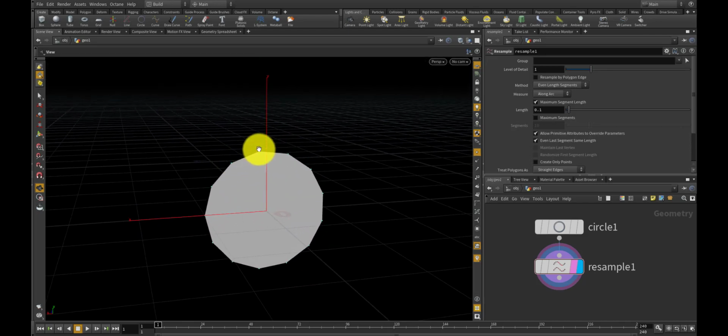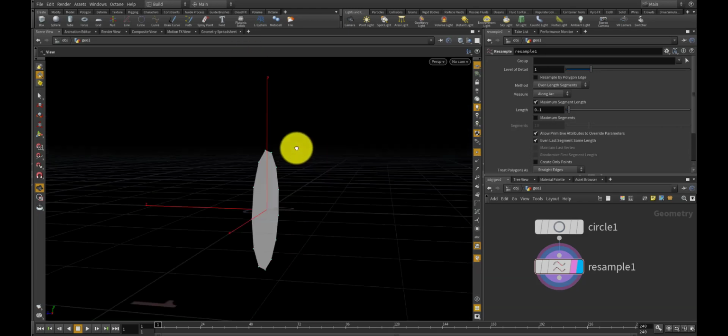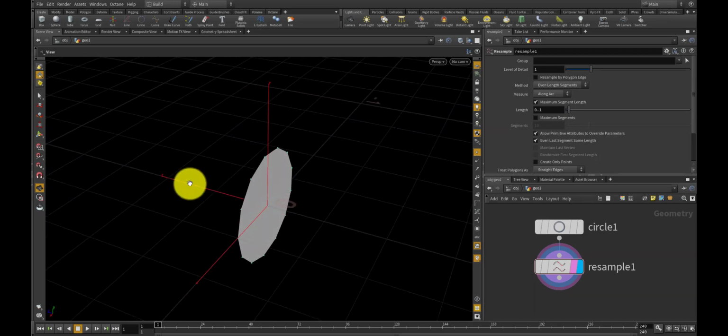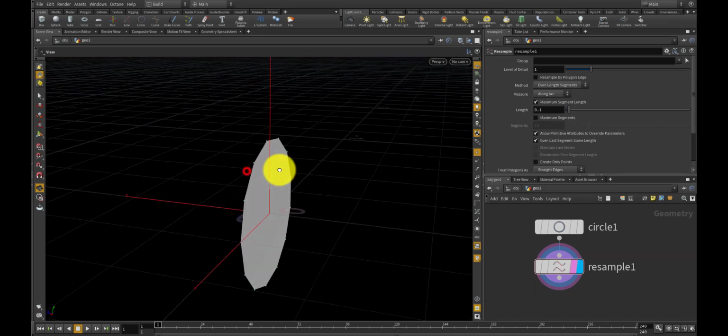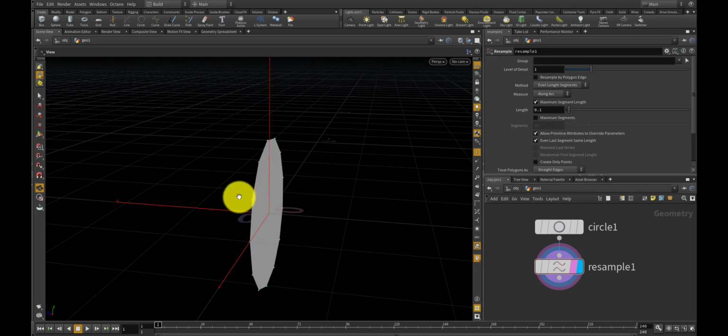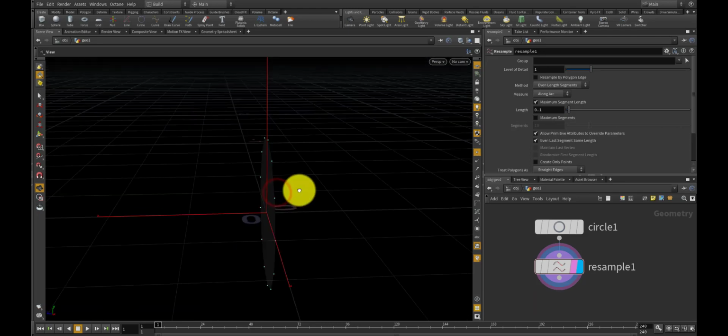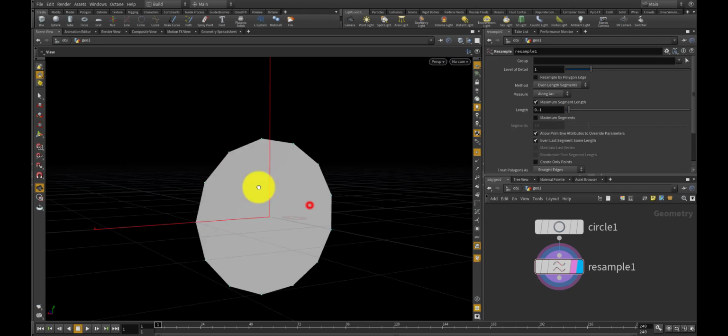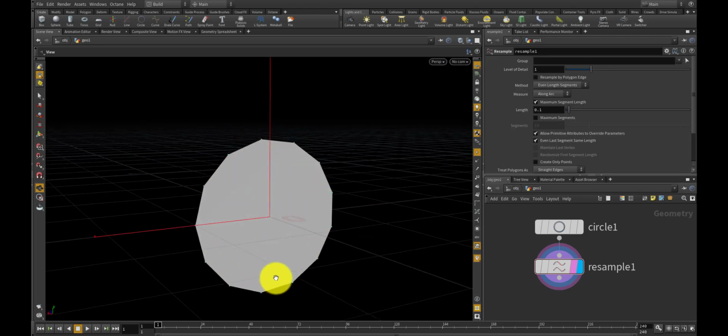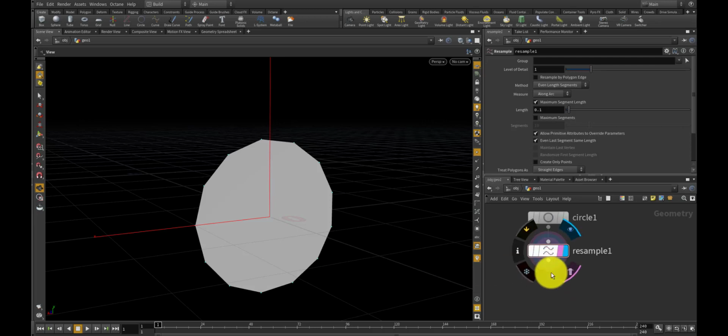So if I try to expand those edges, it's just gonna expand in the XY plane and might not go to 3 dimensions, in the Z axis. So I want to offset each point a little bit in the Z direction, maybe using a sine function, to make it more wavy as an initial condition, so that it will easily go to 3D.